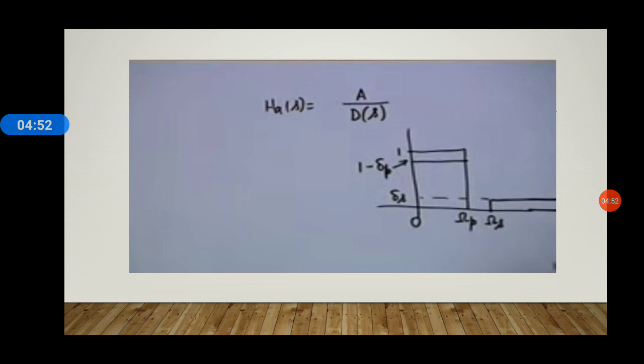What we are to do is always keep a track of omega p, because omega p is the pass band, that is our concern. Omega s, we can make some adjustment with omega s. For example, if we shift omega s closer to omega p, then it is a win-win situation for us, that is better than what we were asked to do. But we should never compromise with omega p. Omega p is sacred and should be satisfied fully.